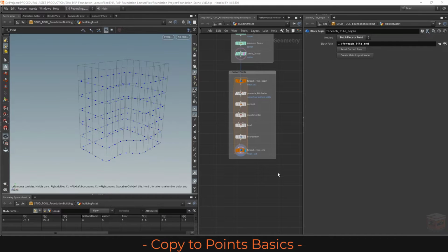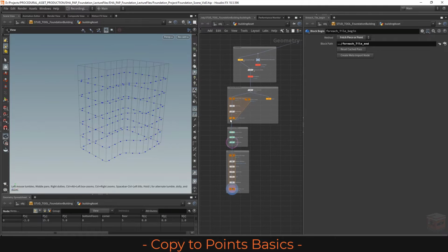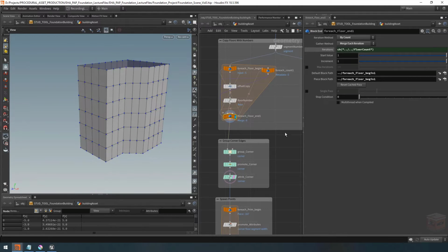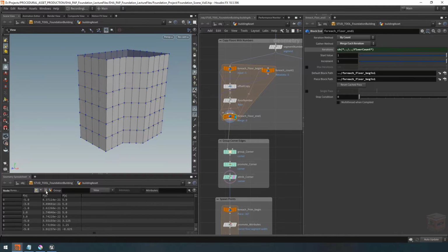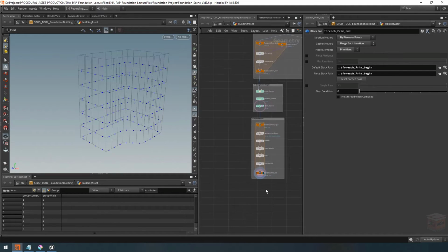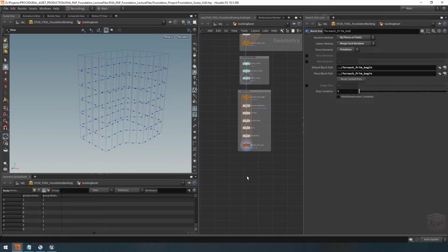Now, before we created our basic wall shell using a simple copying mechanic, but this is just the guide for the height and width of our tiles. And we've actually translated that, of course, into our attributes down here. Now we can use those attributes to regenerate our tiles procedurally. The way we're going to do this is through a for each loop that runs over our spawn points right here.